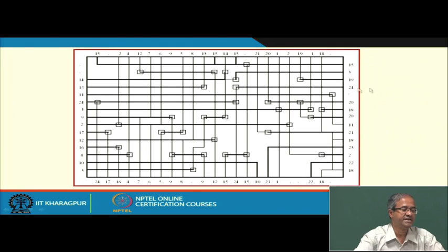Now, that constraint remains that horizontal and vertical lines may be on two different tracks. This is a two layer solution which is shown. So, horizontal connections may be on layer M1, vertical connections on layer M2, and you can have multi-terminal nets as well. Okay. So, this is the final solution for an example switchbox. So, I shall not go into the detail of any algorithm there.